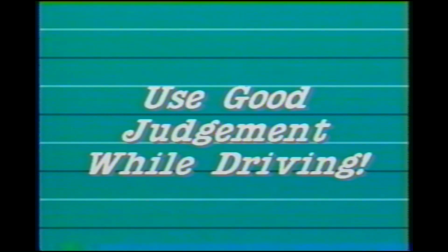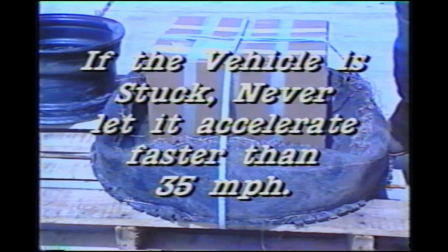Use good judgment whenever driving under abnormal conditions. Free running a tire in mud, snow, or on ice will cause the tire bead to break or the tire structure to separate, rupturing the tire. When a vehicle is stuck, never let it accelerate faster than 35 miles per hour.